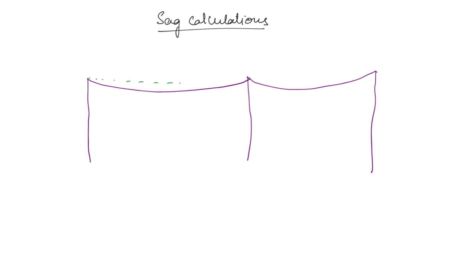If you construct a straight line, let us say, then this distance is called the sag, okay. You can also consider it like the highest point of the tower and the distance of that highest point to the lowest point of the transmission line. You can see it in that way also. Now this sag cannot be too high nor too low.